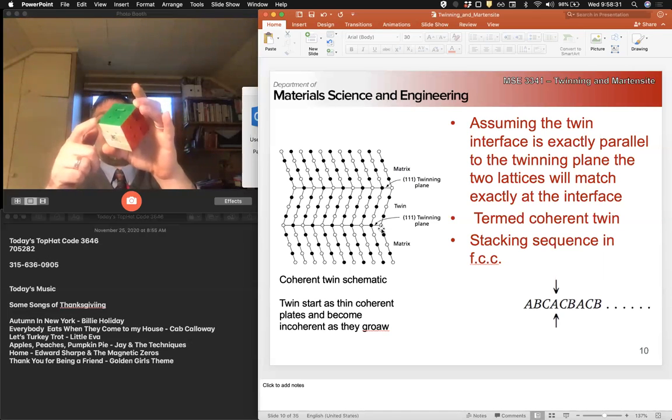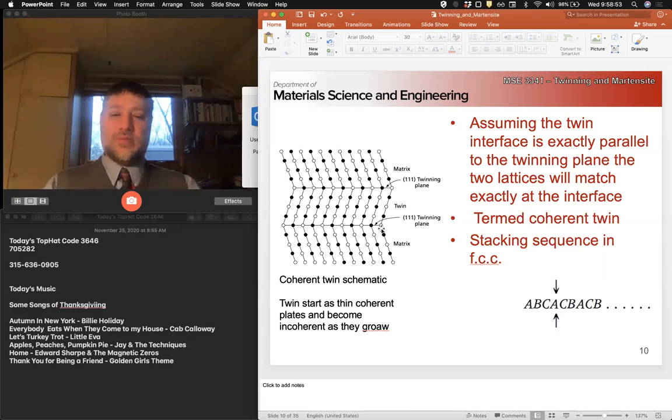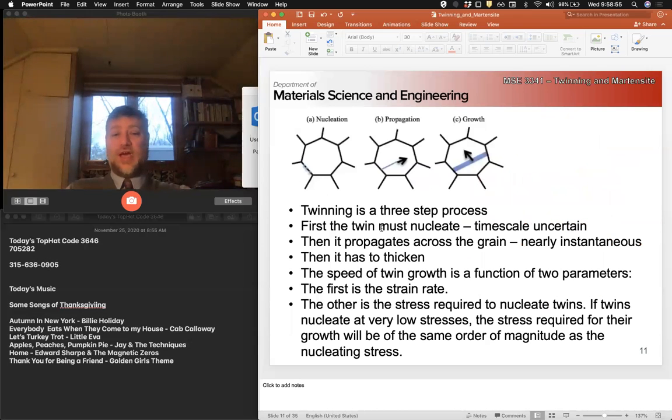And if you play with it, you can maybe visualize that that actually is a mirror plane, or a mirror symmetry, if I'm halfway between two equivalent crystallographic states. I now have a stacking defect on the 111 plane and a mirror on that 111 plane. Okay.